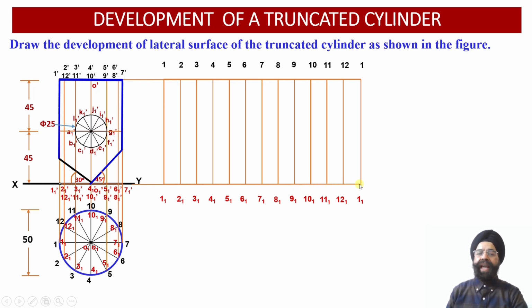Now we can see that this cylinder has been cut by three cutting planes. This cutting plane 1, it is going to intersect with 5 generators of this particular cylinder which is standing upright. Similarly, the right side cutting plane, it is also going to intersect with these 5 vertical generators over here besides the central generator over here. So this point will be common between AIP 1 and AIP 2 over here.